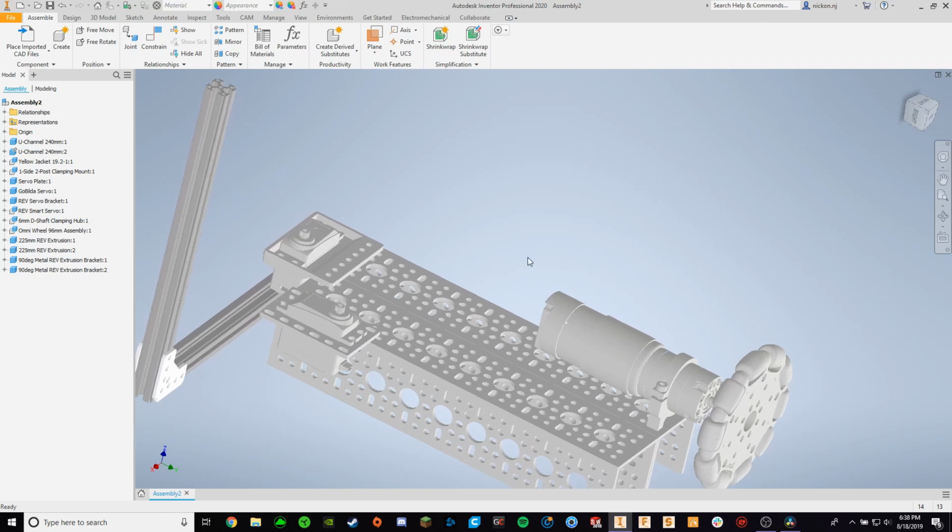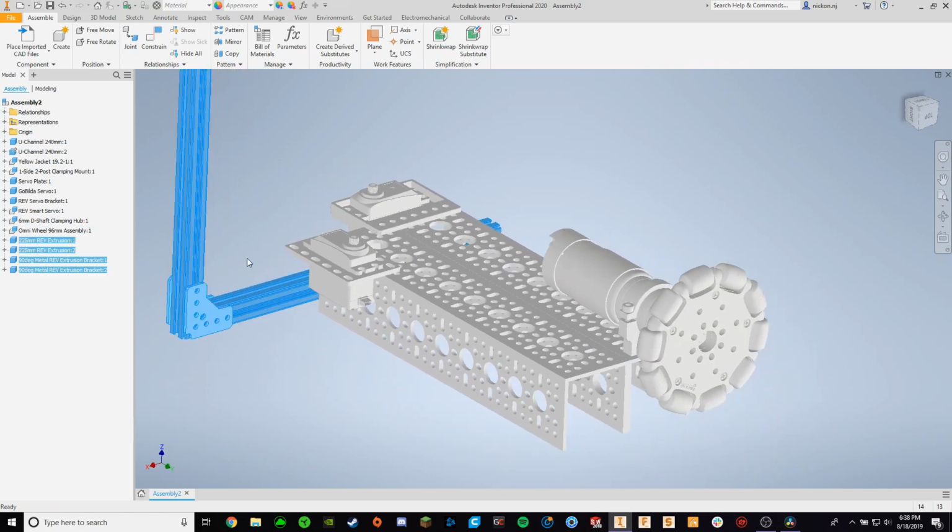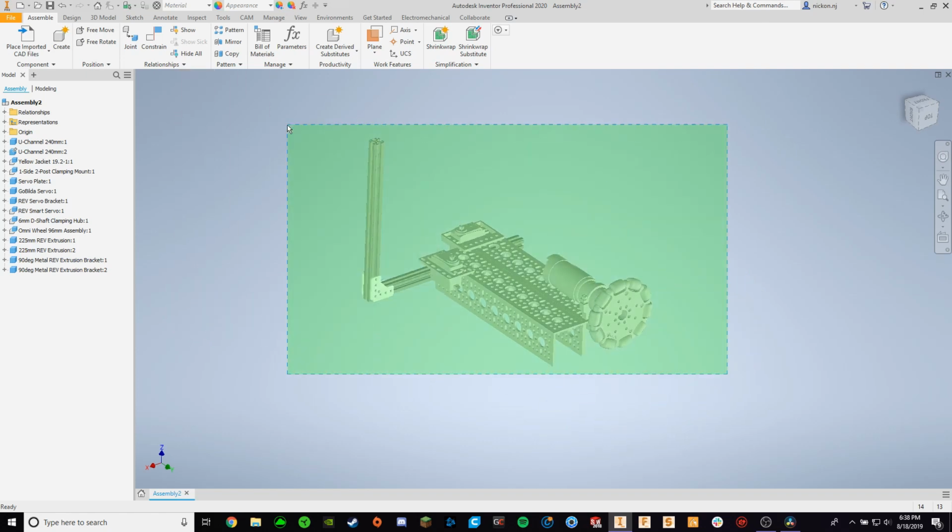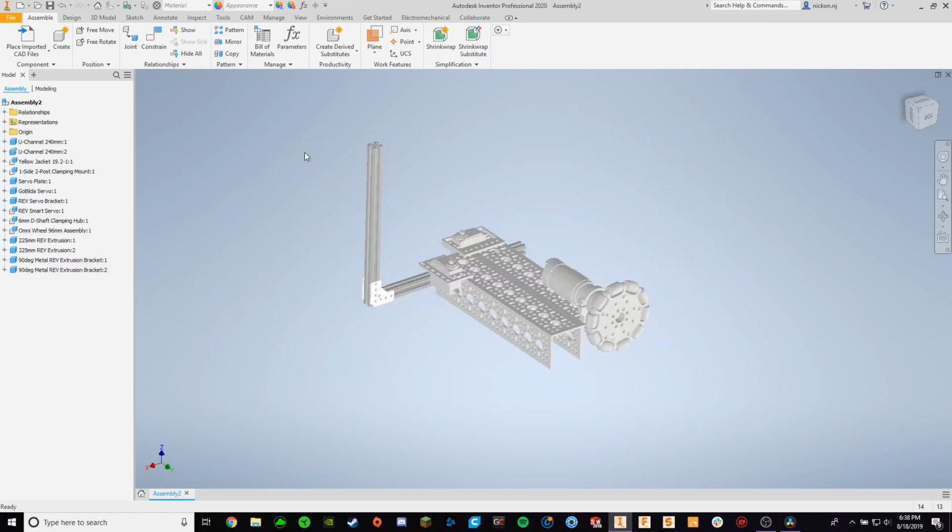And just remember, there are some pretty wrong ways to do stuff, but there are a lot of ways to reach the same effect or solution. I'm sure there are other ways of doing this intersection. Some of them might be faster. But all of this I basically did with just mate constraints for face and axes, and then angle for this motor, and that was it. So it's three constraints, and I built all this.